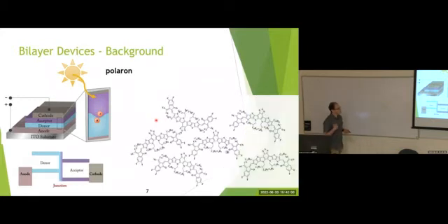However, as I said before, the mobility is very poor, and this is because these materials are molecular conductors, which means that although it may be relatively easy to move the electron on a molecule, it will be difficult to make it jump from molecule to molecule, and it does it by means of quantum tunneling. And we call quantum tunneling in organic electronics hopping.